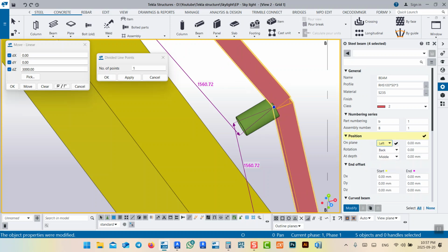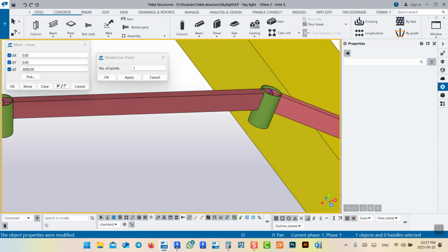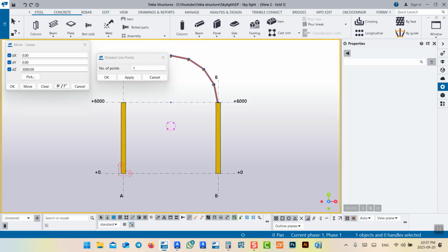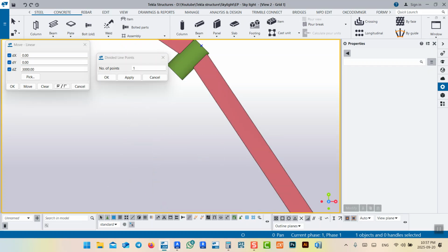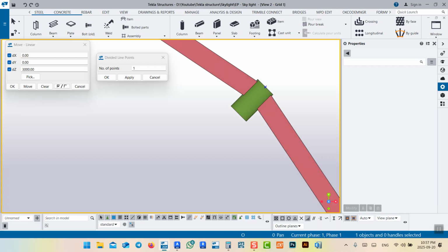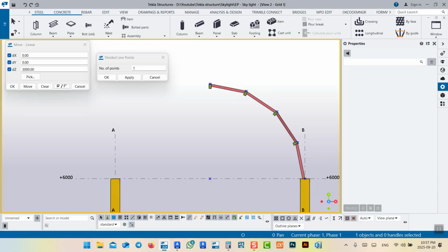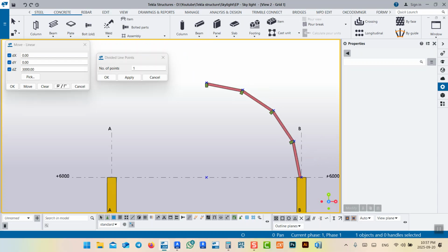Yes, just like this. Yes, we get the point what we want. Why do we put it like this? Because as you know, this area is 10 centimeter, which has more moment of inertia. It has more moment of inertia, which is the stronger axis.